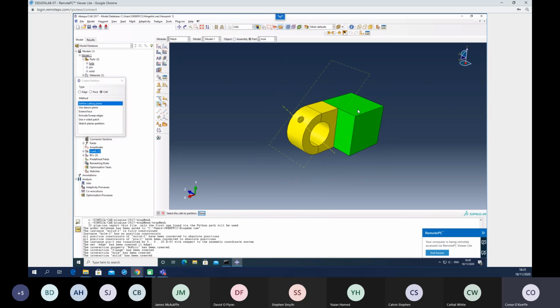So at the moment, there's two different mesh settings defined for each unit here. You can tell that by the different colors, right? So I want to change that. So I use this tab here, which you can assign high level mesh controls, and here you have finer level mesh controls.